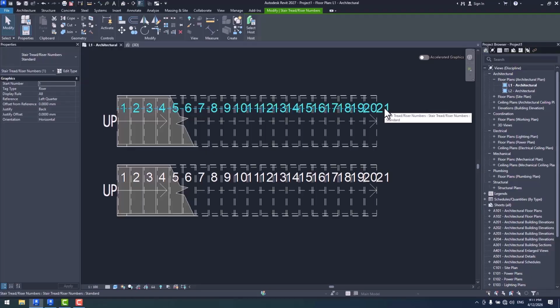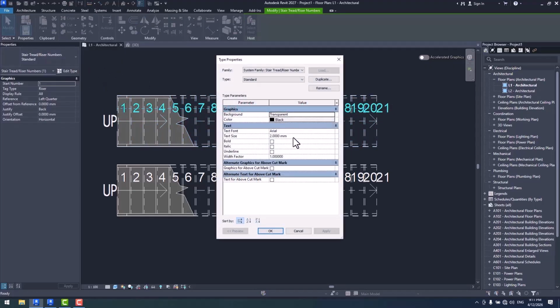Now, though, we got this tab, we got the Edit Type tab, and as I'm sure you already know, guys, when applying a modification from the Edit Type tab, it would be applied on the entire type, meaning on the entire project, if you will. You know, to put it simply, guys, this means more preciseness, more speed, less cost, and even less, you can say, less effort.